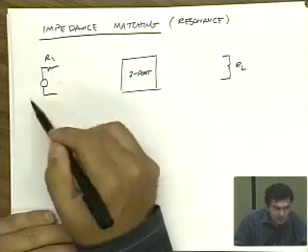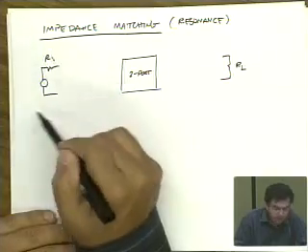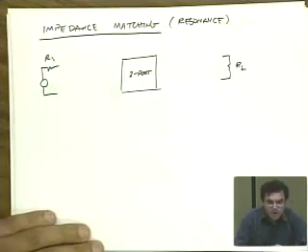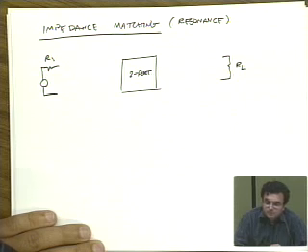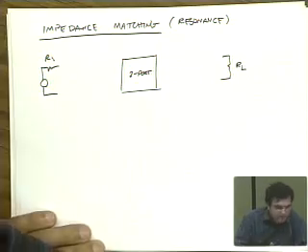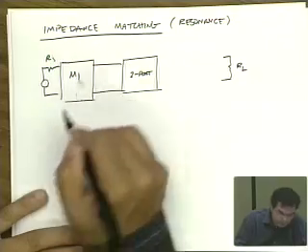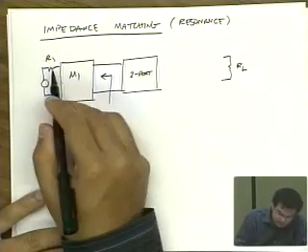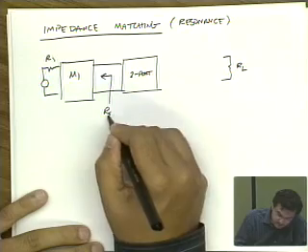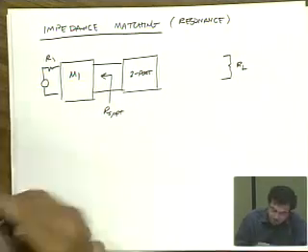For instance, this might be an antenna, and the person who designed the antenna says, well, the best I get is 300 ohms. So your source impedance has to be 300 ohms. And you say, well, actually, I want 10 ohms. I want to be driven by 10 ohms because that gives me better power gain. And the antenna designer says, tough. So what do you do? You actually design a matching network. We'll call this M1 that transforms RS into, let's say, RS opt, or more generally, transforms ZS into ZS opt.